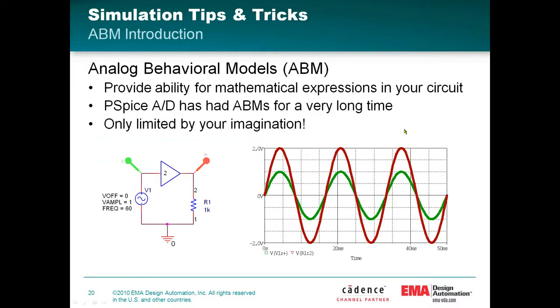There's also analog behavioral models, similar to the concept of driving a circuit with some unique waveform that's not necessarily something you get right out of a standard source. You can create the functionality that a particular circuit will basically be designed to do. Create that functionality in like a mathematical formula. So you do this with analog behavioral models. There's a variety of these models available.